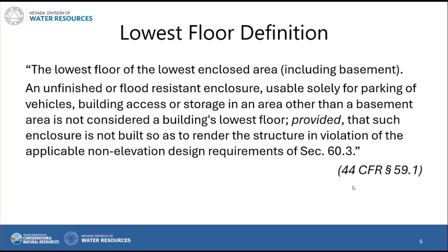It says an unfinished or flood-resistant enclosure that's used solely for parking of vehicles, building access, or storage in an area that's not a basement isn't necessarily considered the building's lowest floor, provided that that enclosure below BFE isn't built so as to render the structure in violation of these other design requirements.